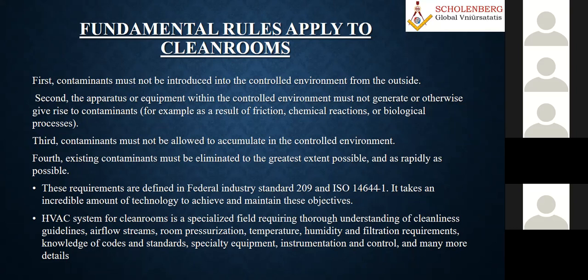So that's what I'm saying: the controlled environment must not generate or give rise to contaminants or any source of additional load. Third, you should not allow contaminants to accumulate. There are limitations for everything, so you have to have a proper airflow pattern, it may be laminar flow or a proper exhaust. Even if contaminants accumulate, on what basis do we remove them, and what protocols do we maintain? And last, as rapidly as possible, any existing contaminant must be eliminated to the greatest extent possible.